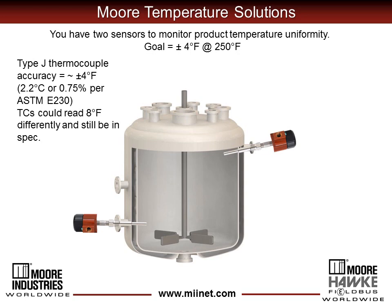If we were to choose a type J thermocouple, because that's our plant standard, we may not achieve our goal. One of the thermocouple standards that we use in the US says the type J thermocouple accuracy is plus or minus 4 degrees Fahrenheit at the operating temperature. So our product uniformity could be perfect, but two type J thermocouples could read 8 degrees differently and cause us to report to operations that we're out of spec.